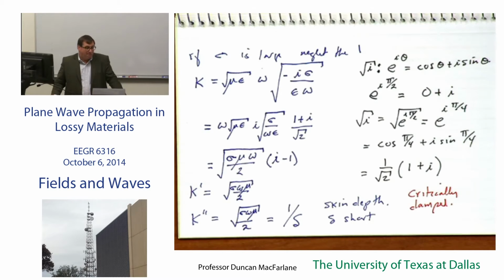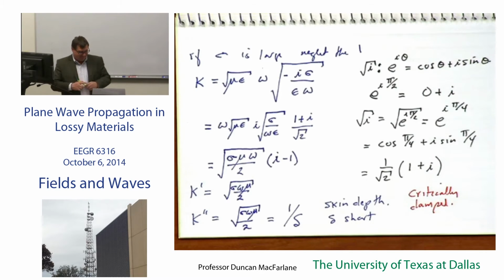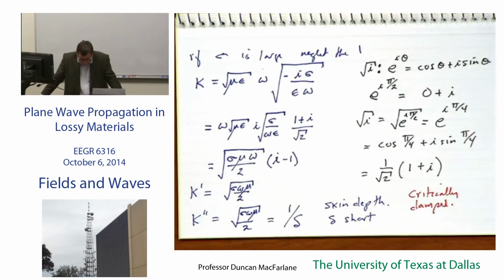Okay. Kind of unrelated question, slightly, just quickly. On skin depth, I've heard that you need to make sure you have enough skin depths to not lose much power or current. Yeah, that's a really good point. But then again, at lower frequencies, they say that if your trace thickness is very small compared to the skin depth, then you're okay.